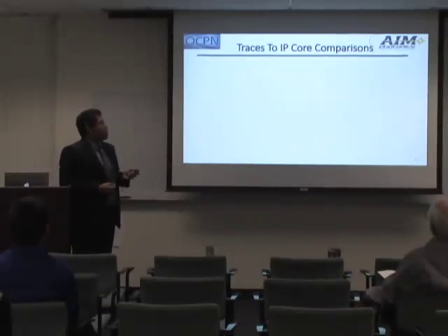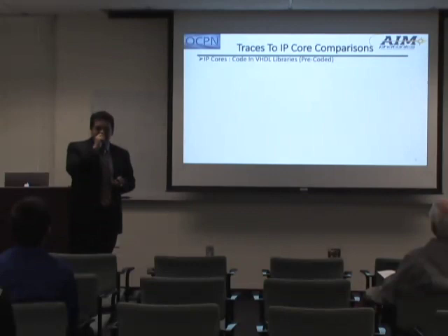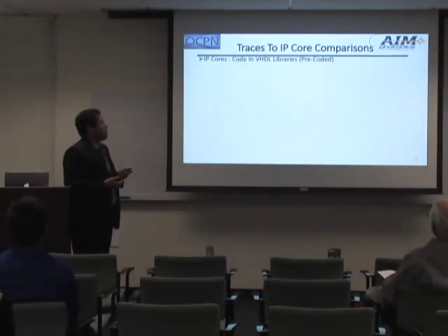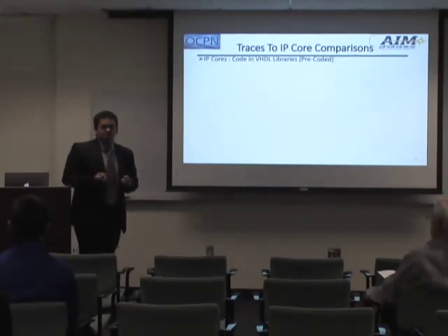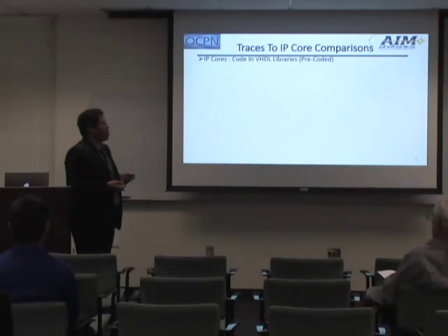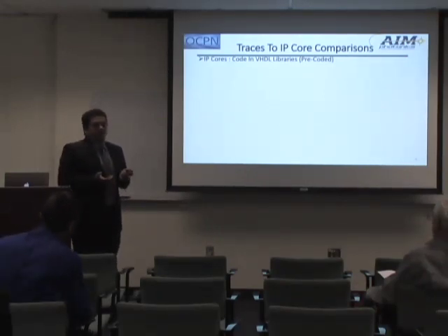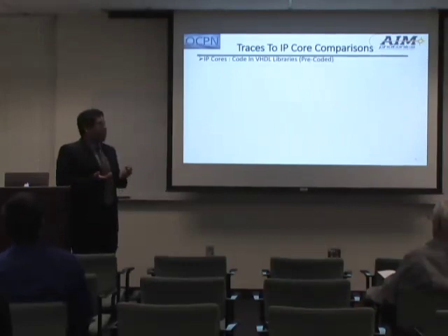And so just to answer that, I've been working with something called IP cores. To simplify, IP cores are pre-coded subprograms in the VHDL libraries that I can use. I can configure certain settings and generate instant code that I can download onto the FPGA to perform certain things. For example, I can use a frequency synthesizer, which is sort of what I've been coding.